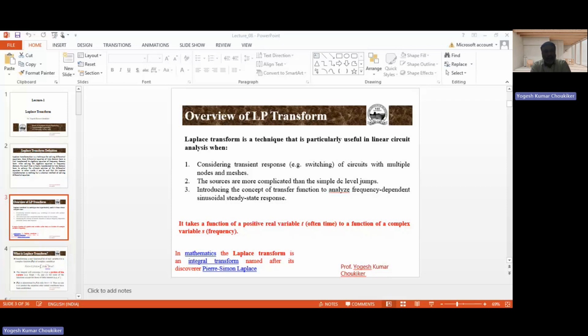Apart from this, we have some properties which are called time shift properties and time reversal properties. Here, if you see, this is our 0, and our time is shifted towards a. So from the point a, the value is 0, and the second one is level 1. For this case, we can write the function f of t is k u of t minus a, and for the time reversal, we can write k u of a minus t.